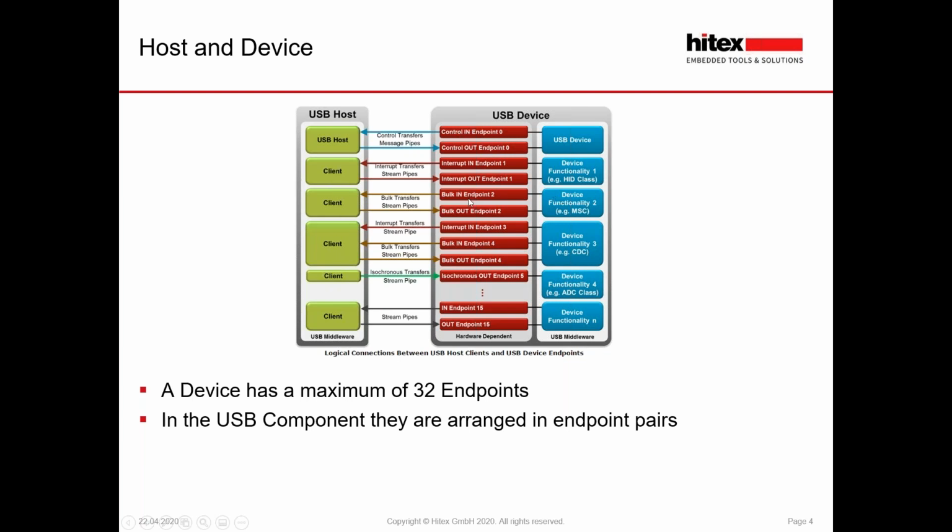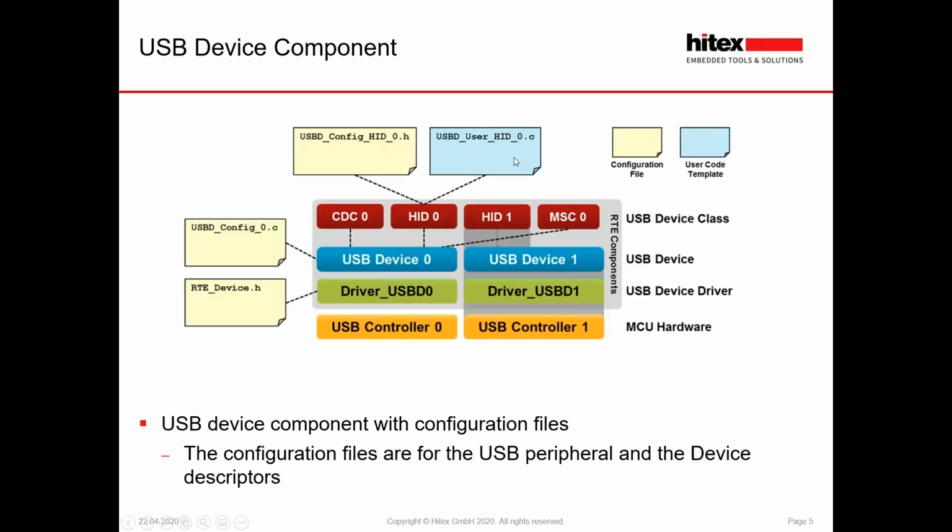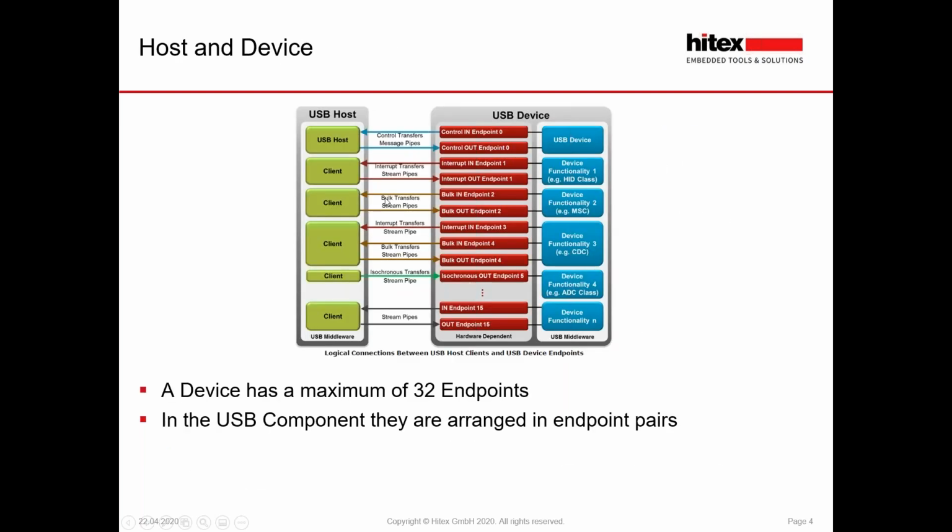All of the naming within the USB stack is centric around the PC. So we're going in that way, out that way. So we have a number of pipes. Typically, I think the USB standard specifies up to 32 endpoints. And we have a control pipe at the bottom, and this is always at endpoint 0.